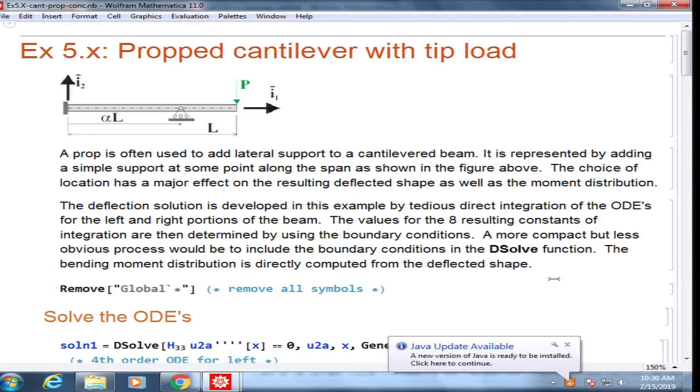The slope on the right end of part 1 should be equal to the slope of the left end of part 2. The slope cannot be something where the beam deforms like this. There cannot be a sudden jump, right? So this is for displacement: the first order derivative of displacement should be continuous so that it's smooth.